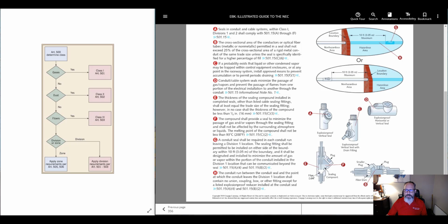So going down in this EYS is going towards where the gases are at and the explosive environment. And what you do is you put a fiber material in there to dam it up around the wire, and you have to put it in through this little small threaded hub you pull out. And then you mix up and pour in the sealant compound.